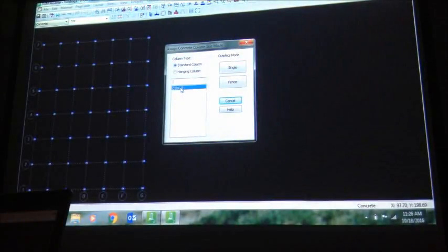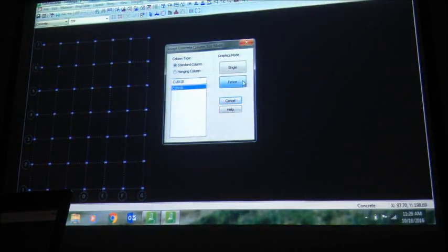So one thing you can do now is give a column size, or you can do it later, doesn't matter. So maybe column, I can assign a size. Now a lot of columns you can change properties that I will show you. You can delete columns, change materials. You may want to add something in the middle, you can do that. So let's do assign size and standard column. So all my columns are already assigned, the shape or the size.